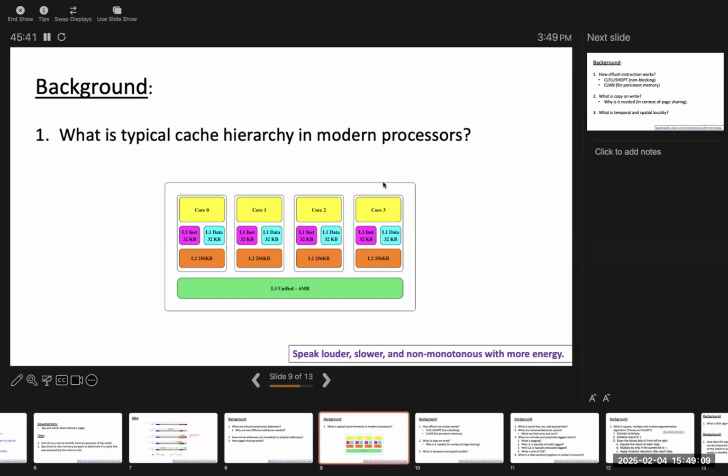Anyone who wants to answer how splitting L1 improves performance as compared to the case where we do not split the L1 into data and instruction cache? Quicker access to its own L1 on each core. But everyone has its own L1 anyway. Even if it is not split, every core still has its own L1.